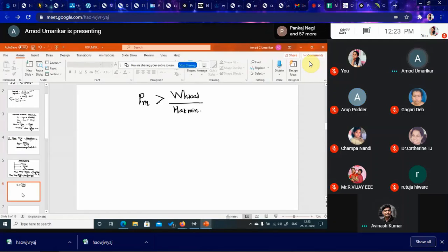So this upon this is energy and this is hours, so we will get power for a given PV size, because PV size is available not in watt hour, it is available in watts. So we have to find out the final size in watts. Okay, so this is how we can do the example.